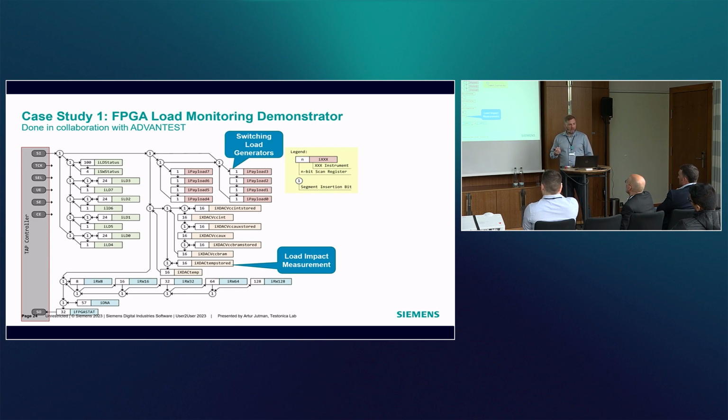instrumentation. While you execute the test, it may be executed correctly, so you get your pass results. But while you do measurements at the same time, like measuring temperature and voltage, you may see abnormal actual behavior during the test, and that may be an indicator of some faults that are hidden inside, which were not discovered by just functional tests. So, some sort of indirect discovery of faults.